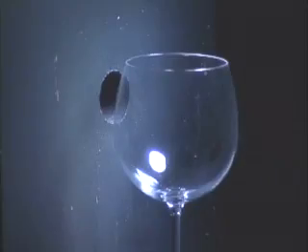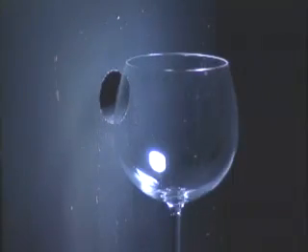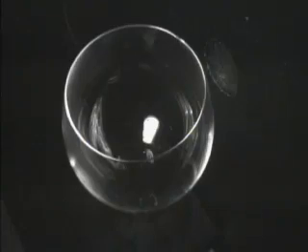And I'm going to drive the system now at very low amplitude, at a frequency close to its resonance. You can already see that the glass is moving. I'm going to increase the amplitude. You see it moving? I can go a little bit over the resonance, and under the resonance, you will see it stop moving then.